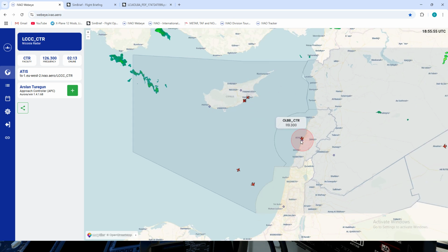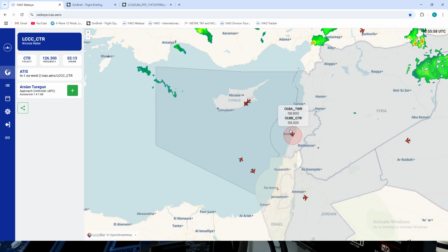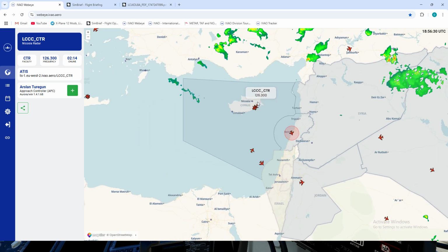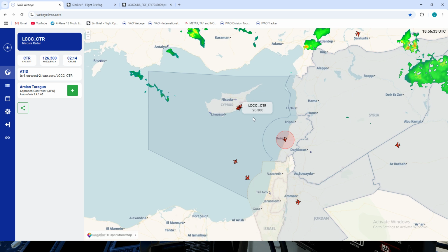Notice the red represents an ATC logged in as a tower, and those shaded areas are a control area. ATC actually has layers. It's not like one division controlling all the traffic. There are layers of ATC, starting with the delivery, and then ground, then the tower, then the departure or approach, and then the area control. Each one of those has different responsibilities to attend to.